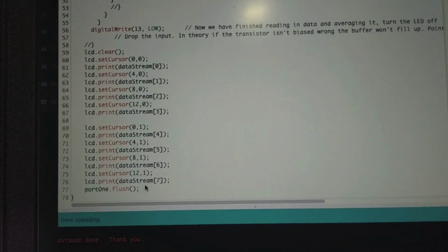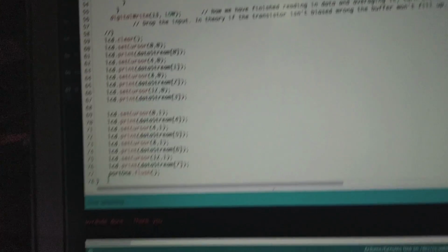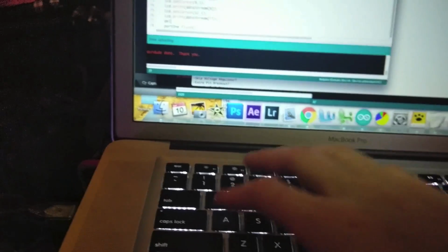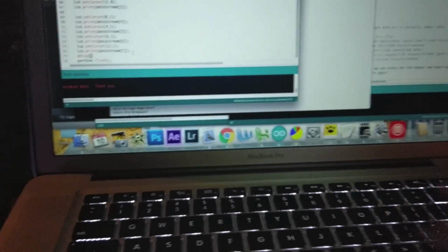And then we just do some stuff to print it out. I don't know if flush is necessary or not, but it was in Phil's code, so whatever. So yeah. If I wanted to, I could probably add a very short delay. We'll say a delay of, let's make it real short. Let's just make it 1 millisecond, see if that fixes up this blinkiness. So we're writing, we're reading, good, and it makes it a little more legible. Let's bump up to something that should actually affect it, like 10 milliseconds or something. Hopefully that doesn't slow down the read process too much.